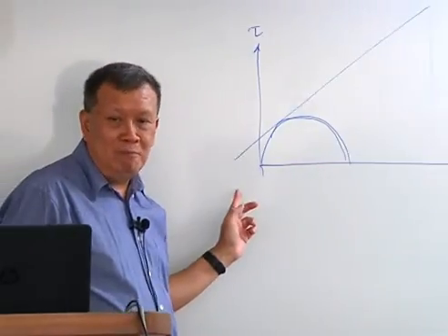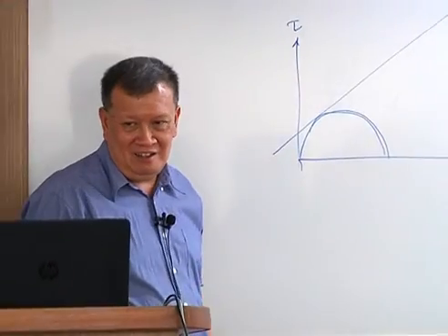So the idea of zero effective stress in the lateral direction should never occur, because you want a high lateral effective stress to squeeze the sample out like toothpaste. Right? So in fact, you want a very high sigma r'. The sigma r' has to be higher than sigma a'. So in fact, your sigma r' is the major principal stress, not the minor principal stress. You get what I mean? So that problem is irrelevant. Okay?